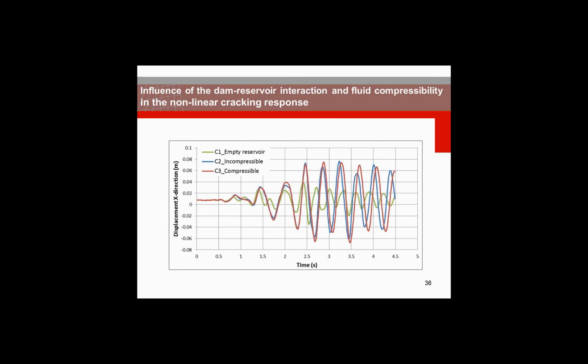Now we are going to present the influence of fluid compressibility in the response of this kind of 2D finite element models. This is again the displacement of the crest in the x or lateral direction, and we compare the model without water, the model with compressible water, and the model with incompressible water.